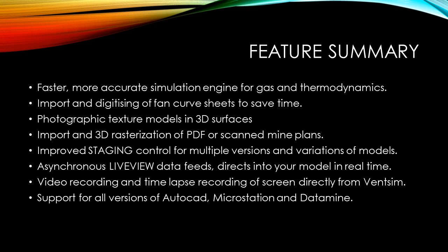Can you import block models into Ventsim 4? If you can export the block model to a DXF file or a graphics file, you can import those block models into Ventsim as a visual surface, but you can't actually use them as a block model as such. So you can visually put those models into the program and look at ore bodies and things like that, but you may not be able to actually analyze that block model as a block model.